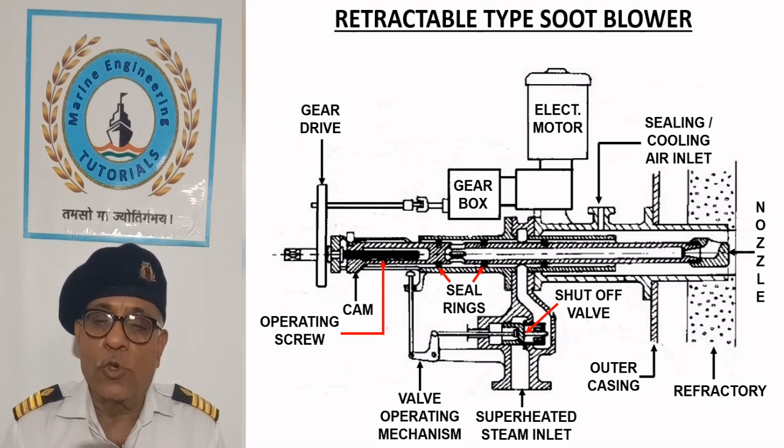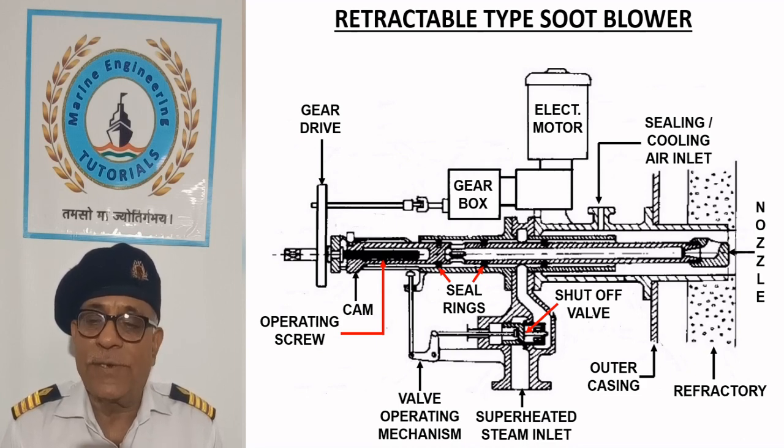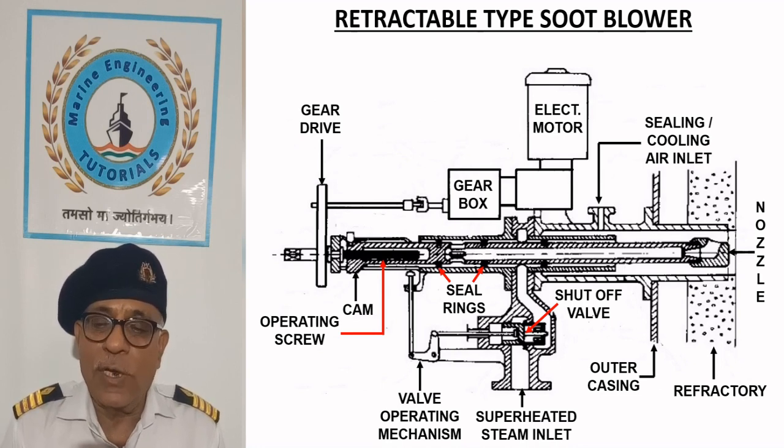Automatic operation is suitable for exhaust gas economizer during the sea passage. However, on conventional oil tankers boiler, manual operation is preferred during the cargo discharging as inert gas plant has an interlock with the operation of soot blower.